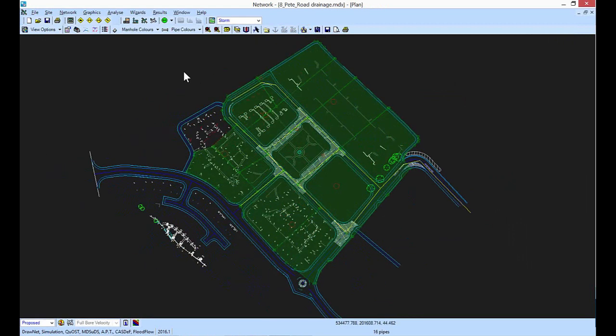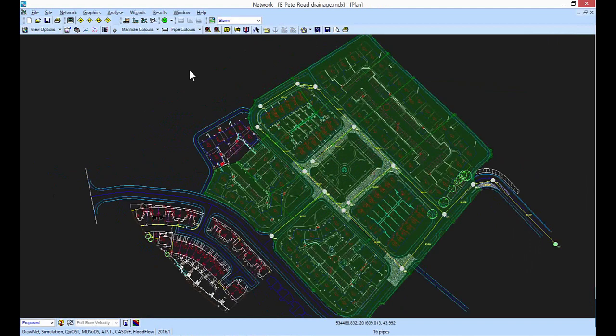I've loaded in the surface data. So all the surface data is known. And here you can see, I hope you can see this on your screens, there's a lot of green area. If I click on the green, you'll see these are the sub-catchment areas entering into different manholes. But just stepping back from this at a glance, you can see that all these areas are covered, but there's a blank. So in other words, I've missed something.